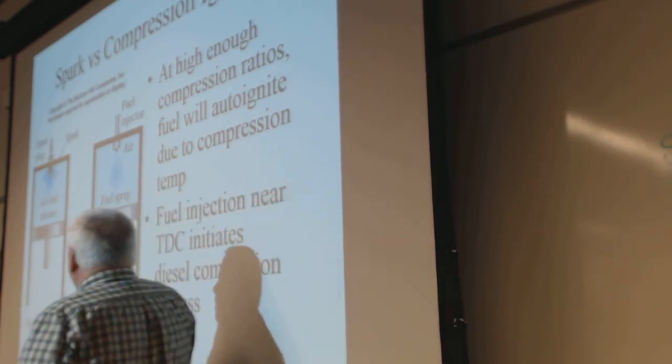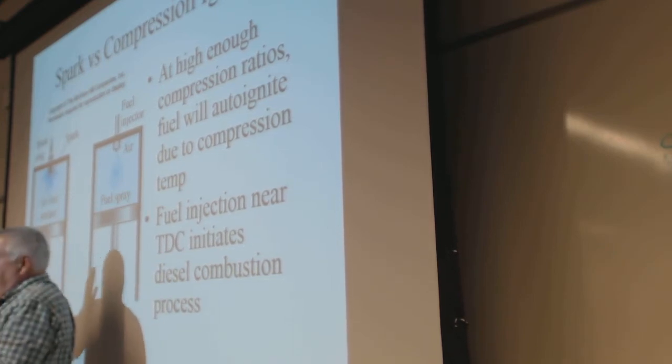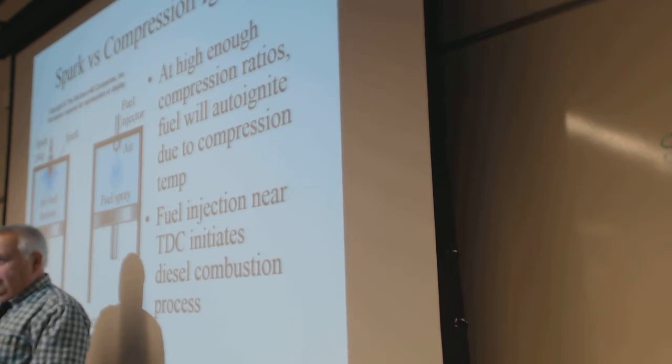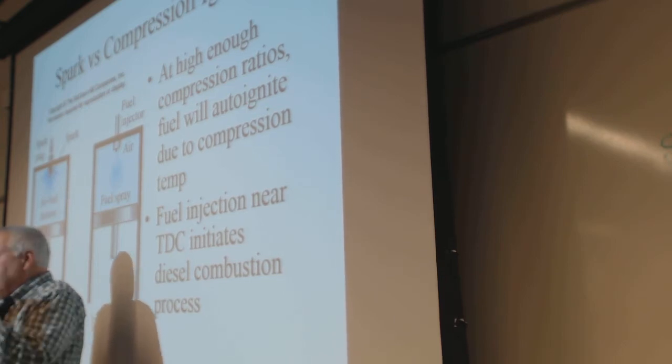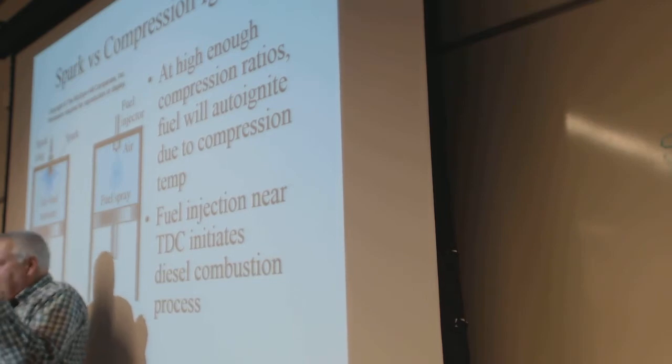One reason for that is the way they control how much power your engine has. On a gas engine, they put a throttle plate. What's the throttle plate do? It restricts the airflow. What happens when you restrict the airflow? You have to pull against the vacuum to bring the piston down all the time.